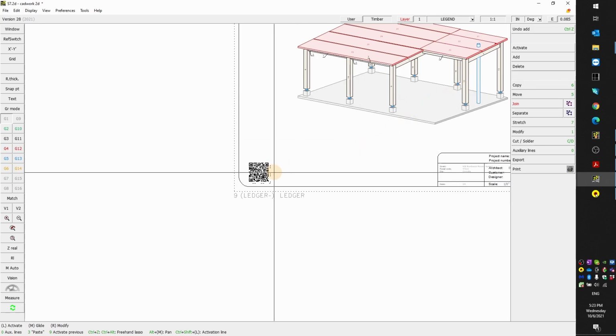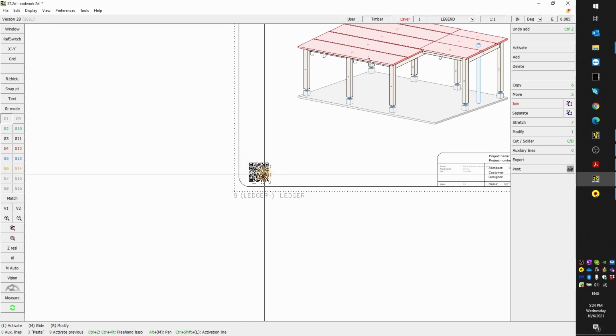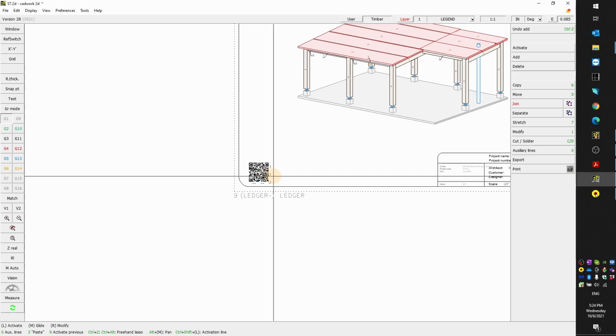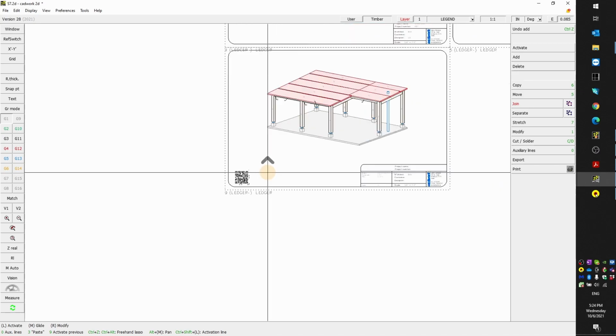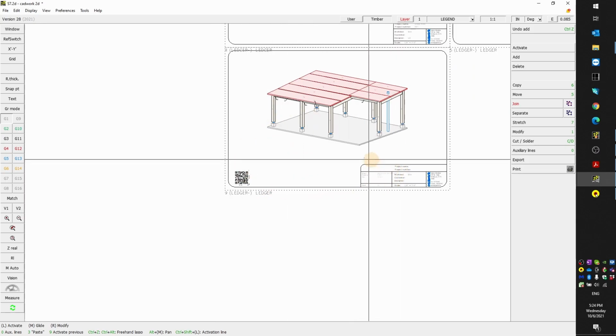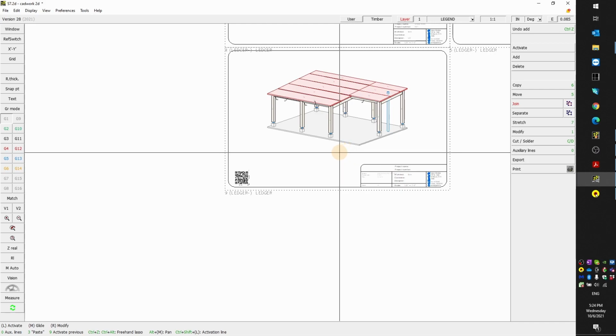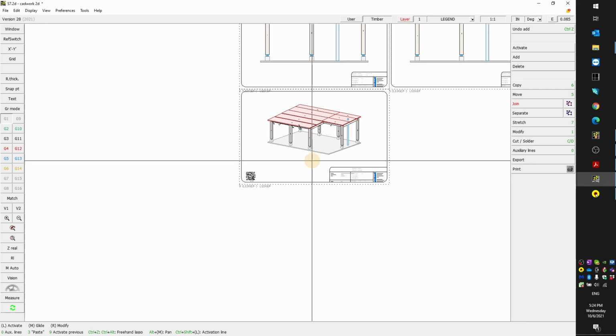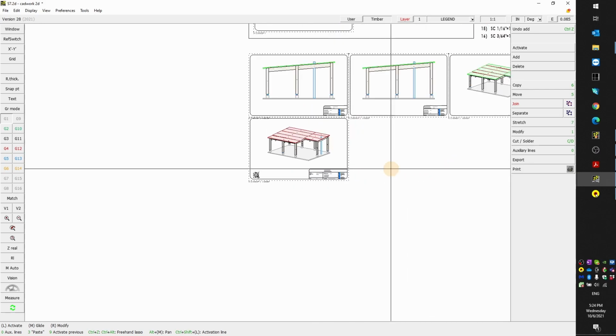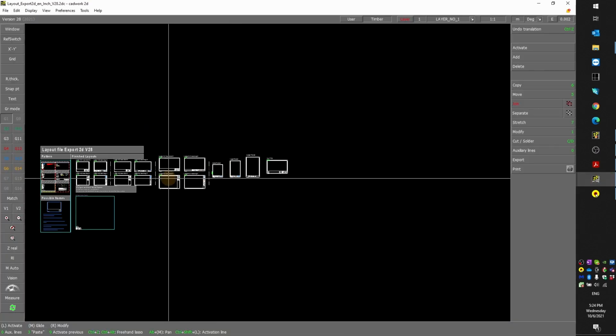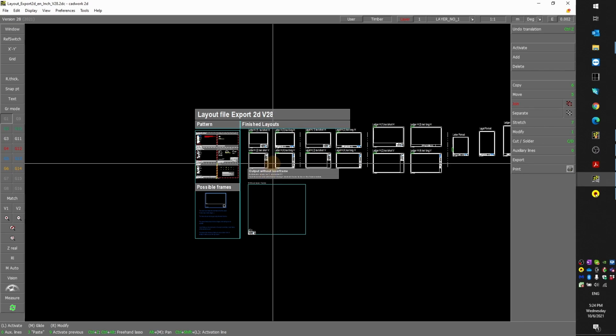Note that also in piece by piece shop drawings, you can have the QR code, so you could add data about the part itself, so including the weight, the machine on which it should be produced, the size of the part, the location where it should be installed, like story, etc. So that can be added in the QR code, and it can also be linked with the WebGL. So I think that's enough for the semicolon export.